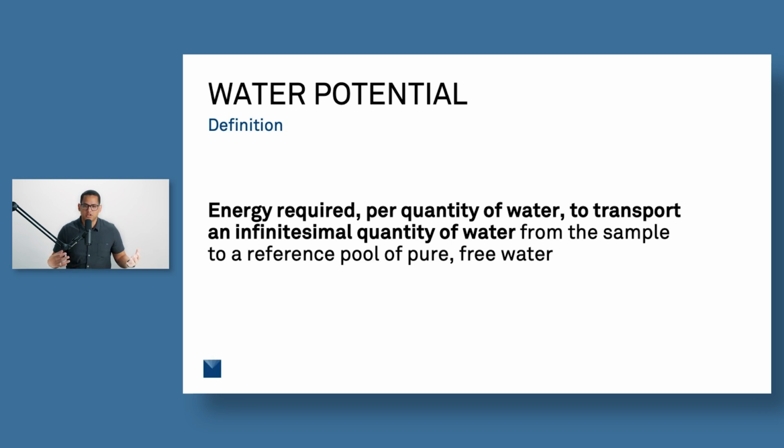Okay, so we can all understand that. From there, it goes typically as a negative value. So as that water becomes more bound, whether it's being bound physically by the soil or chemically, the water potential decreases and it becomes less available. So that's what we're looking at when we're talking about water potential. It's essentially the availability of water and how easy it is to pull out of the soil or how easy it can move out of the soil.